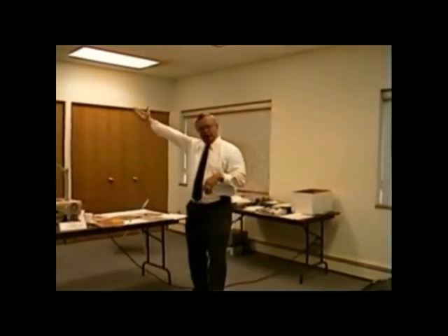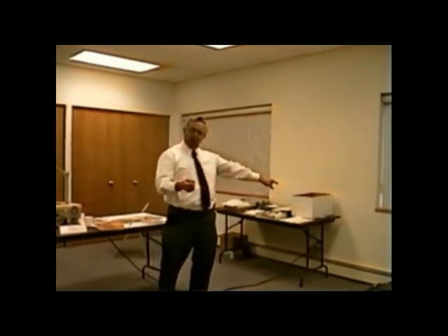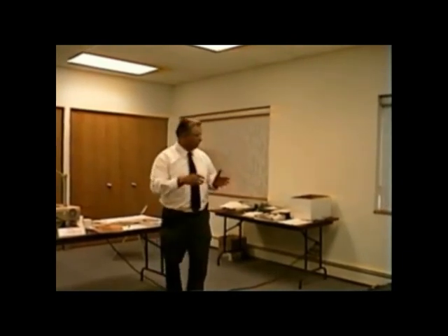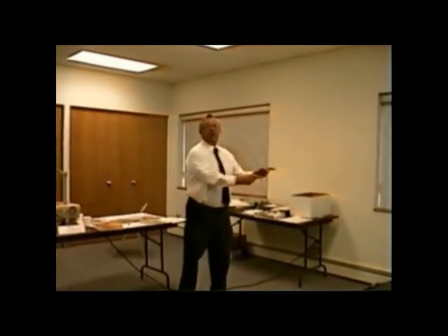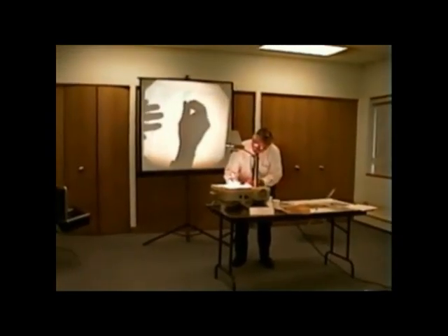Now, carbon monoxide, though, is part of our business today. And it's a good part of the business. If the customer says, you're coming out on your annual clean and check for my furnace, would you also check for carbon monoxide? That's a terrific part of the business. You take your carbon monoxide tester, you zero it outside, and then you walk inside the house. If you get carbon monoxide readings, go and find it. Go over to the register where the furnace is and see if the furnace is producing carbon monoxide. But the point is, we're not asking you to take a carbon monoxide tester and stick it into the flue of a furnace to check for carbon monoxide. Okay? So, let's go back and let's say that question number 20 is NA.